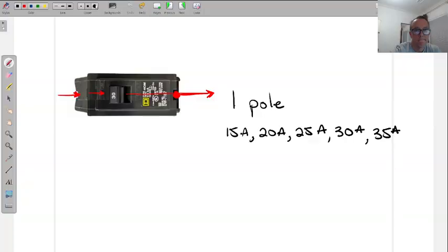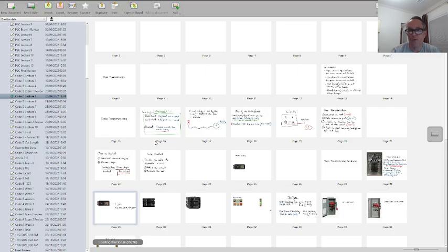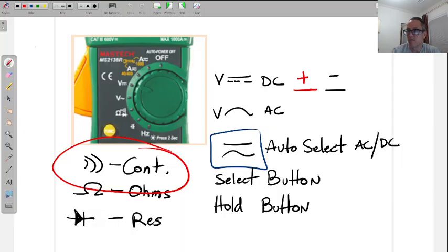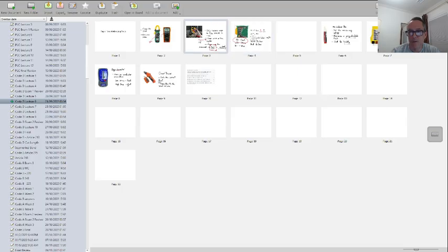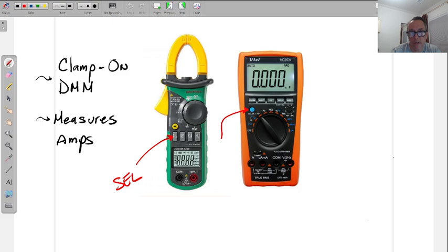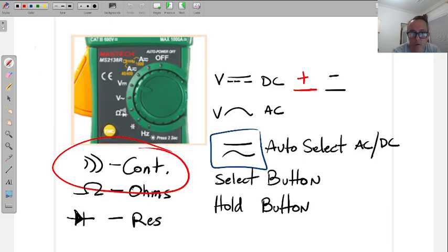When you check for amps on your multimeter, what setting is that? Okay, so for our multimeter amperage setting, I'll give you more of these notes tomorrow. You're going to set it to amperage, and it depends on your meter. You might only have one amperage setting. Mine says 40 amps and the other says 400 amps. So it depends on the circuit that you're going to be measuring.